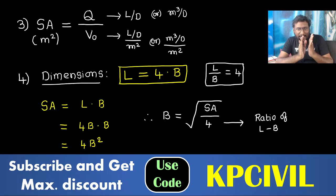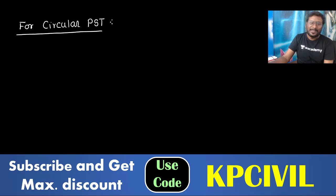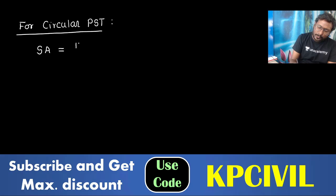So if it is a simple rectangular tank, L is equal to 4B, and B is equal to under the root of surface area by 4. If it is a circular tank, for circular primary sedimentation tank, what can we take? Tell me, for circular PST, surface area is equal to pi by 4 d square.